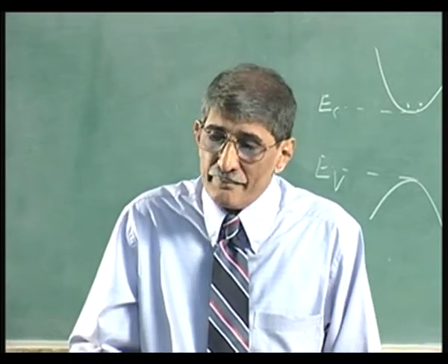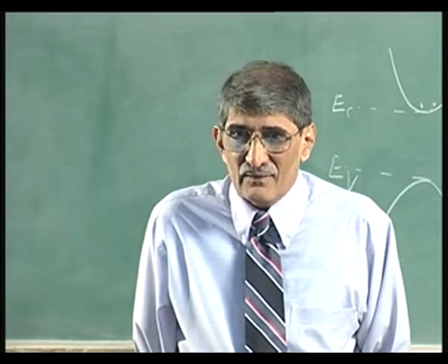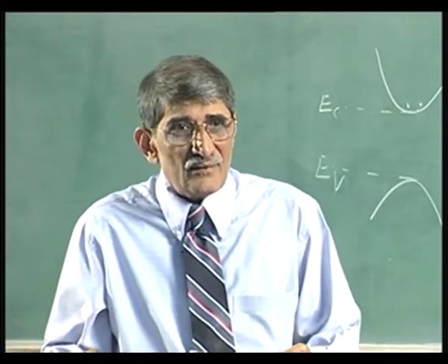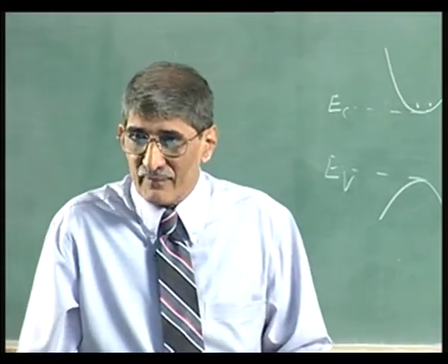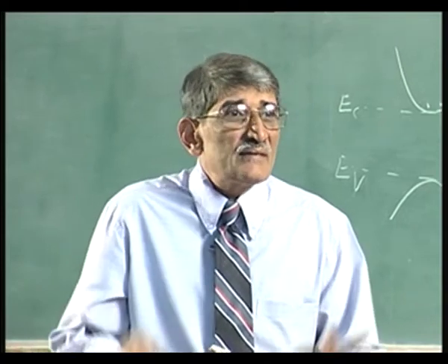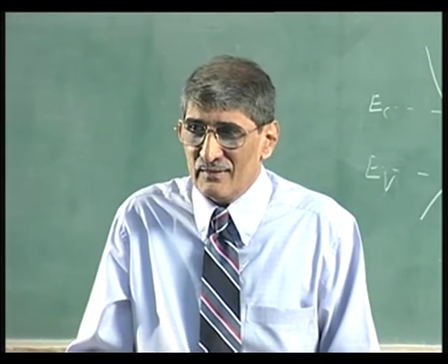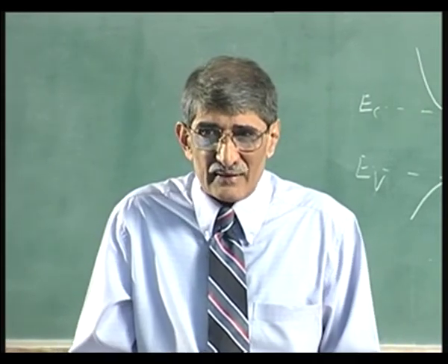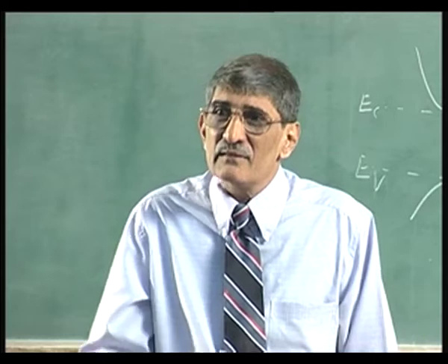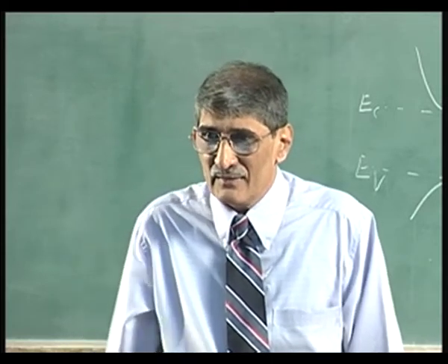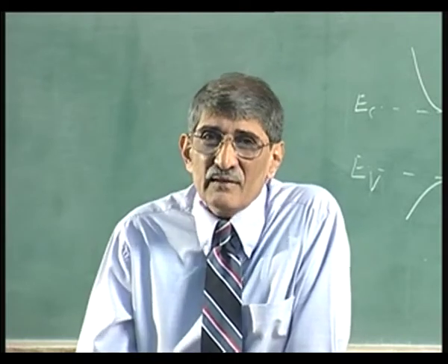Second one is, it is difficult to make ohmic contact onto wider band gap materials. So, you will have to put another material on AlGaAs which has a lower band gap to make the source drain contact. Source drain contact is ohmic contact. It is always difficult to make ohmic contact onto a wider band gap semiconductor. I think we have understood that long time back, because if it is a wider band gap material, the phi BN will be 2/3 of that, that is large. So, higher band gap means it is difficult to make ohmic contact.